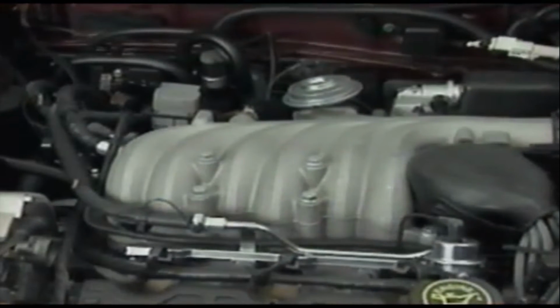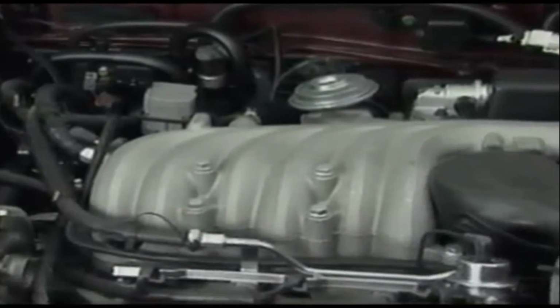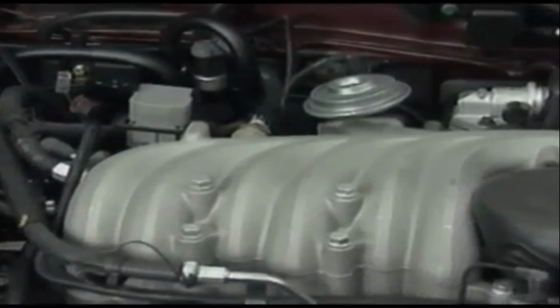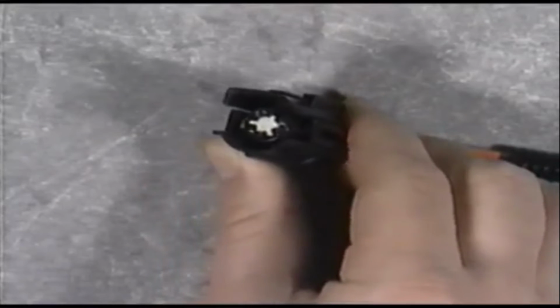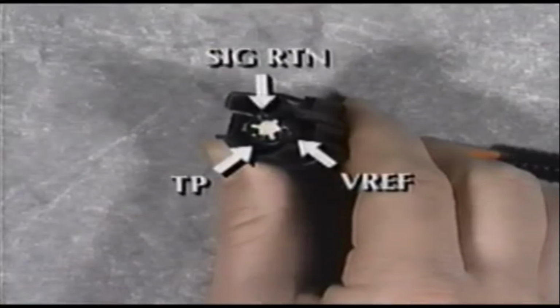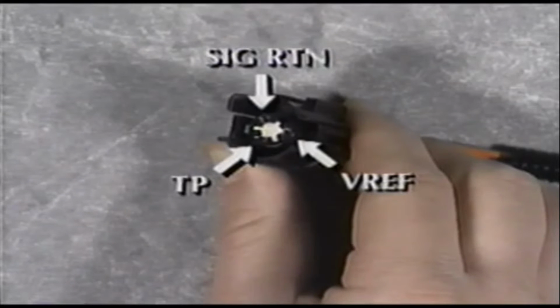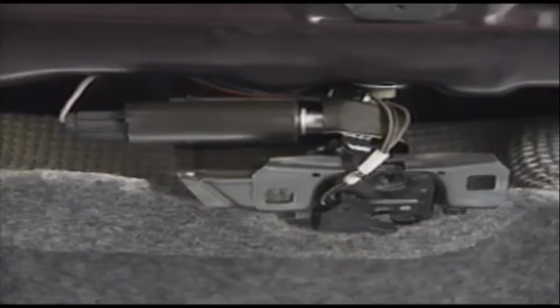In these circuits, the components often have a distinct polarity. That is, they are sensitive to the direction that current passes through them, or which side is grounded. Many connectors, then, are designed to ensure that they are connected correctly, so the components will operate properly and to avoid damage to the circuit and the components themselves. Some locations where polarity is important are sensors and solenoids.